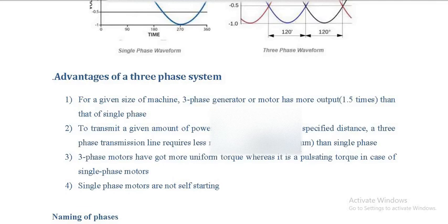The reason behind it is simple. When you use three single phase supplies, it will be two lines, one live and one neutral, for each of these three. So phase neutral, phase neutral, phase neutral. Likewise you will have 6 wires. In case of three phase, it will have 3 line terminals and 1 neutral, so it will be R, Y, B and N. Only 4 wires will be required. So that is just to give you an example. What is seen is that the material required in case of three phase supply is quite less than if we use single phase for the same thing.